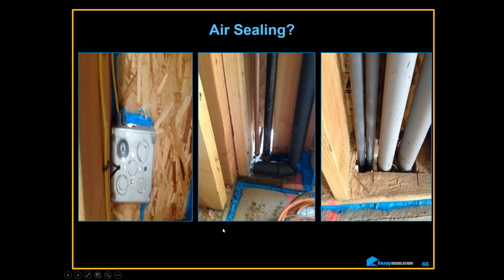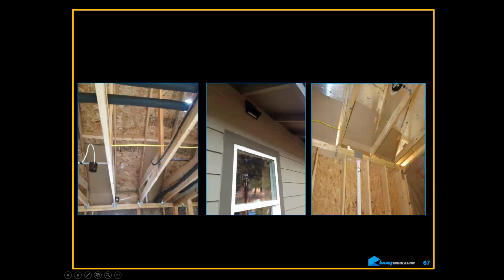But they sealed the plate. Great. Doesn't work. How much insulation are we getting in this cavity? Not very much. These are design problems, guys. And it's a problem for inspectors. It's a problem for builders. It's a problem for all the trades. Other issues. This one I really love. Let's put the kitchen exhaust right over a vented window. I really like that. That's a really good idea.